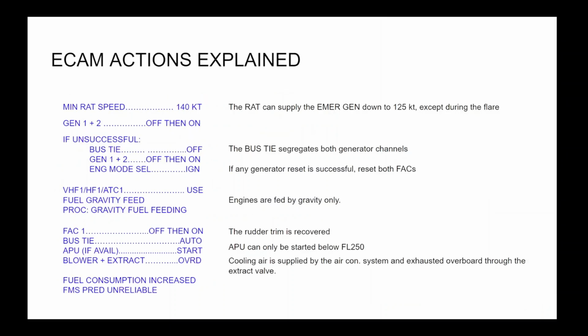Here is what you will see on the Ecam initially when you enter emergency electrical configuration. The Ecam also has these actions, with some further explanations of each action. We will be referring to this later in the practical demonstration.